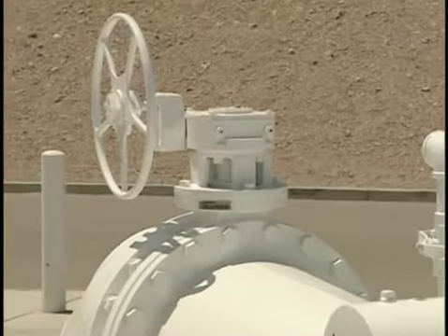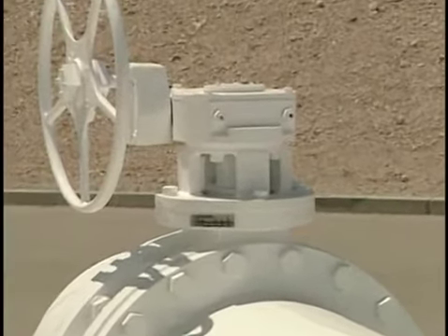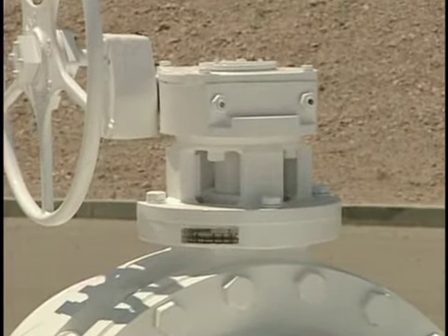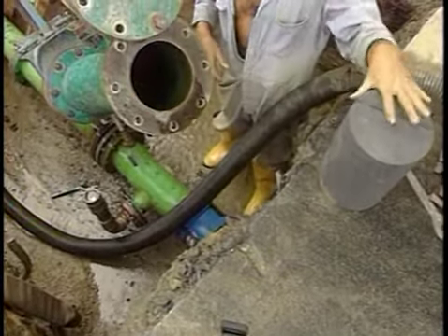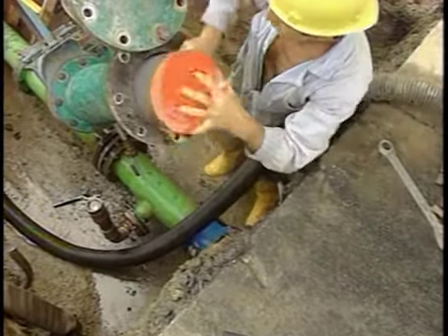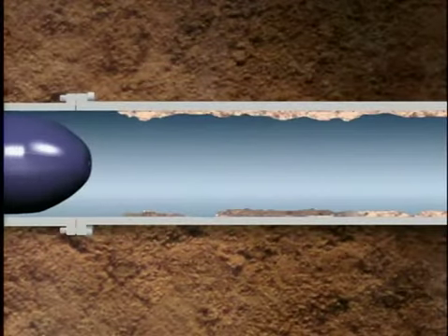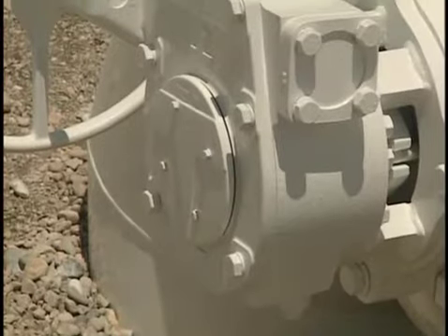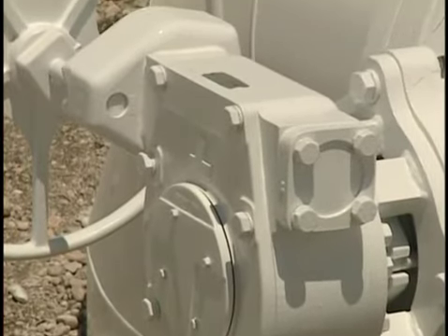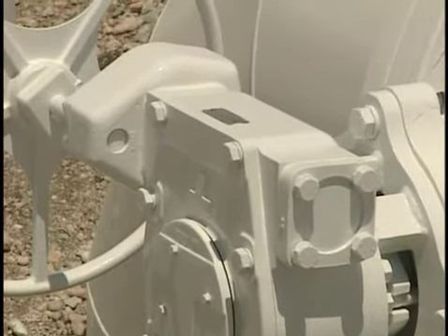Most distribution system butterfly valves are equipped with geared valve operators to make operating large butterfly valves easier and less risky. However, if the water main should ever have to be cleaned with pigs or swabbing, a butterfly valve would be a serious obstacle. Butterfly valves are primarily designed for on and off service. They can be used for occasional throttling, but if used for prolonged high-pressure throttling, the disc will eventually vibrate until it's damaged.